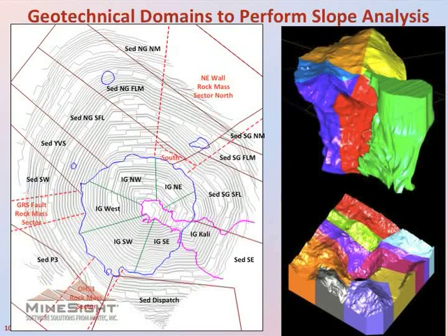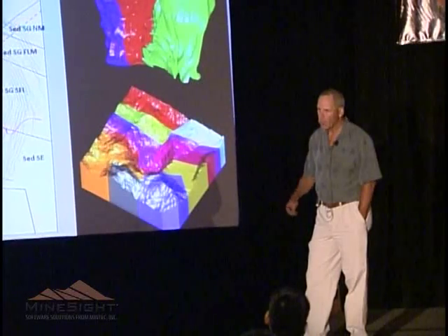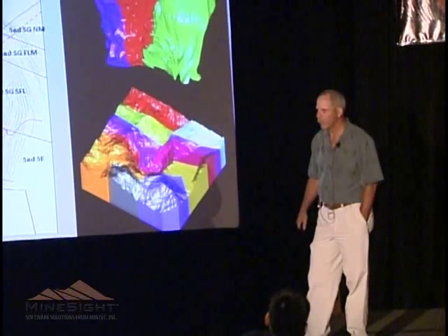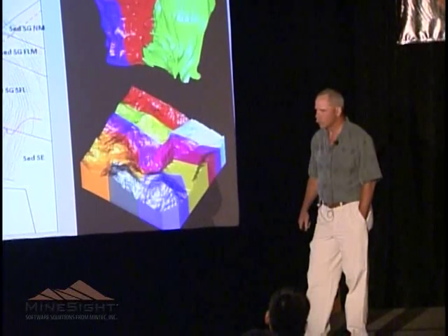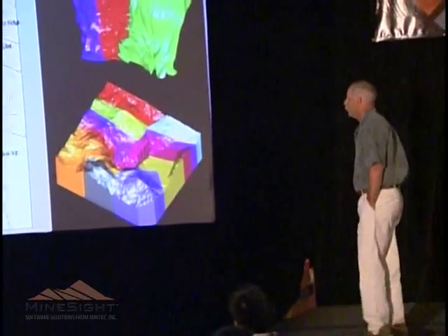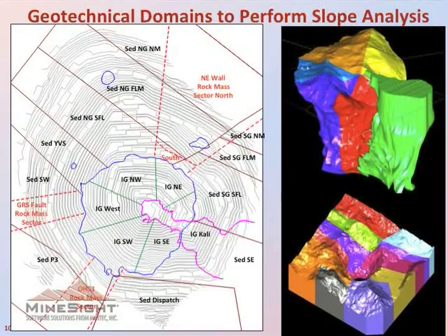Geotechnical domaining is used quite a bit, based on the pit wall orientation, and the domains have to do with the structural domains. In this case, there are quite a few domains, and we'll make solids or just code from polylines. Typically, because it is in 3D, we'll usually build these domains into solids.